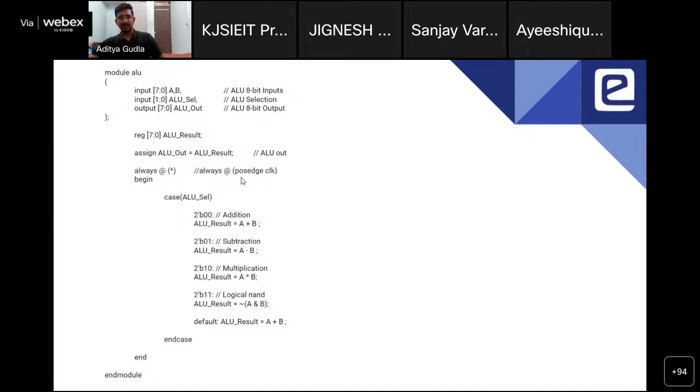So that is basically the sensitivity list. For our particular case, ALU is a combinational circuit. It is always sensitive to its inputs. So if I write star, that means it is sensitive to A, to B, and also to ALU select. Whatever variables are present inside this always block, it is sensitive to those. That is the meaning of this star: it is sensitive to all the values. So whenever there is a change in any one value, this always block is executed.